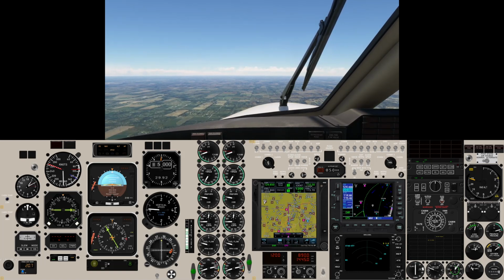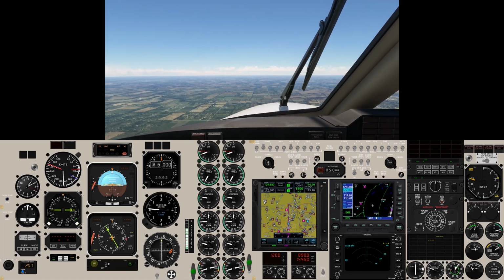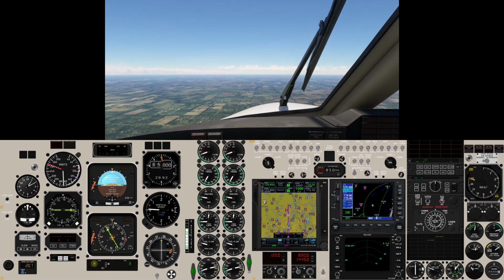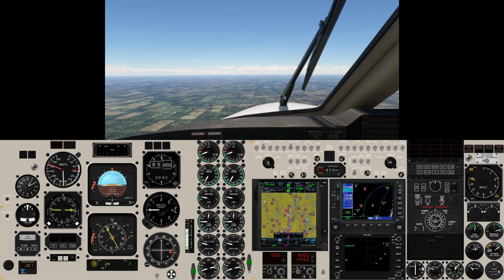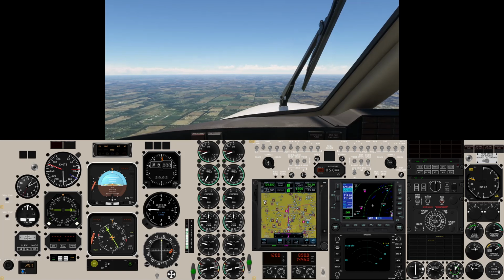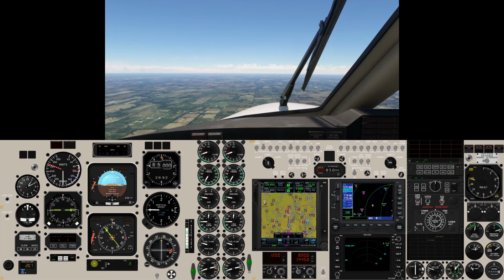Then to the left of the altimeter, there's a fast direct button, an analog clock, a turn and slip below that, a little 2-inch one, and then a gyro slaving module, so you can go into DG mode and then just use the buttons to offset.